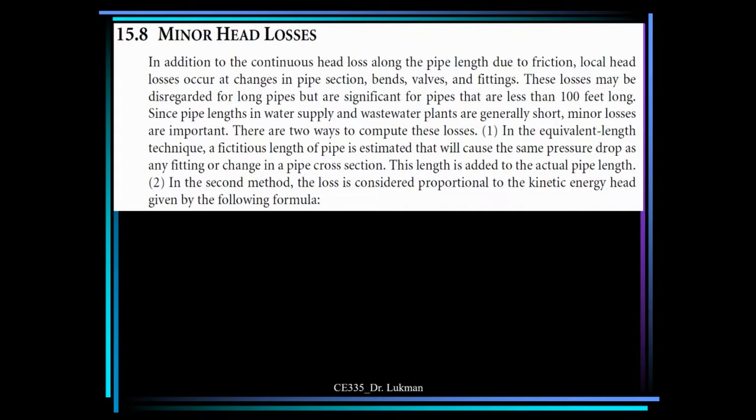And at bends. The pipe section can decrease, and it can also increase, an expanding section. In both ways you have head loss. And you have it at bends, whenever you have valves and fittings. These losses may be disregarded for long pipelines, but are significant for pipes that are less than 100 feet long.